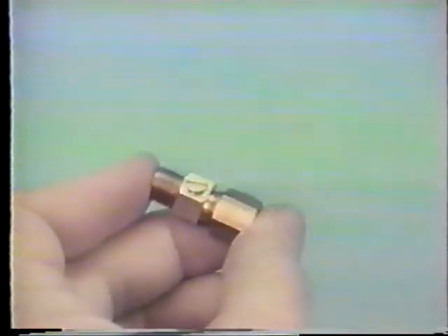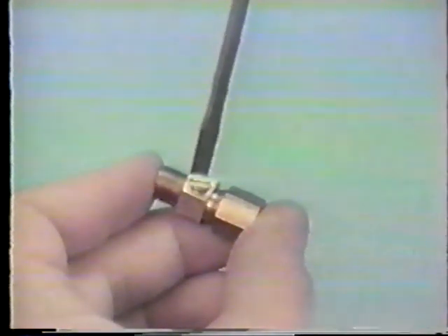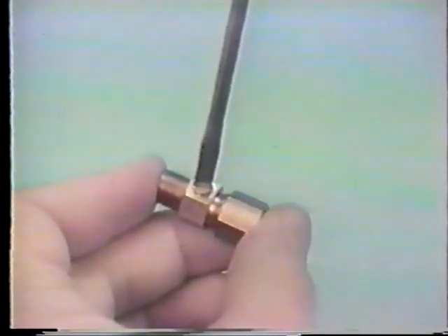When this controller is used as a low limit in a fan system, it is necessary to order an adjustable external restrictor. This restrictor can be adjusted to provide the appropriate amount of air to the control system. To check calibration, measure the ambient temperature at the sensing element and adjust the set point dial to match that temperature. The branch should be 9 PSIG. If not, turn the zero adjustment with a 1/16-inch Allen wrench until the branch pressure returns to 9 PSIG. Now, return the set point adjustment to the desired set point.